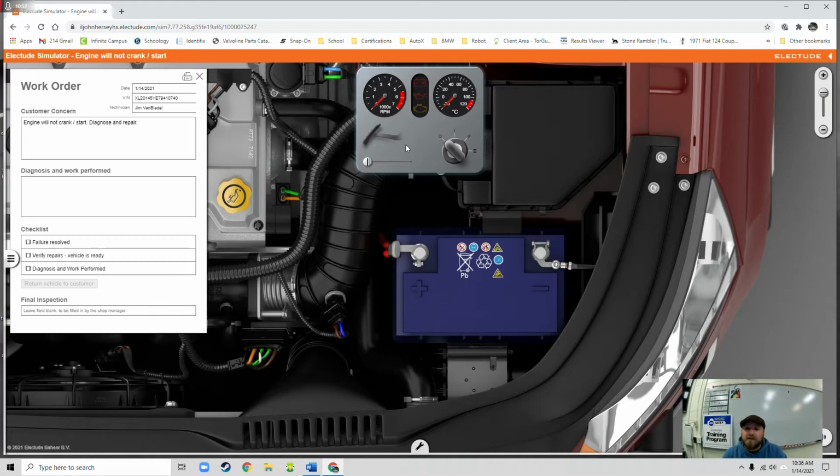And some of those codes are active, where it throws up the check engine light. If it's a really bad one, it'll flash your check engine light, like knock. But sometimes it just remembers something weird that it saw. And it's not a major emergency, but it still stores that information. As a technician, we need to go in and double check the computer to make sure it doesn't see any issues anymore, and then also wipe its memory so that it doesn't keep thinking about those issues, I guess.